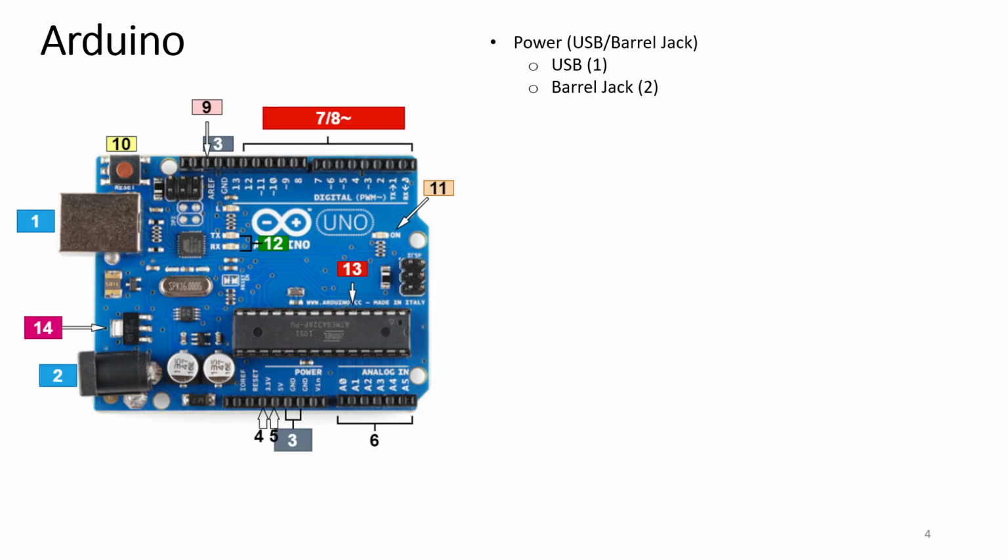So, a quick note is that you should not use a power supply greater than 20 volts, as you will overpower, and thereby destroy, your Arduino. The recommended voltage for most Arduino models is between 6 and 12 volts.